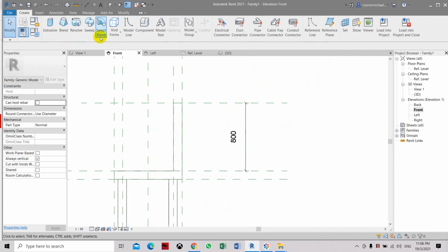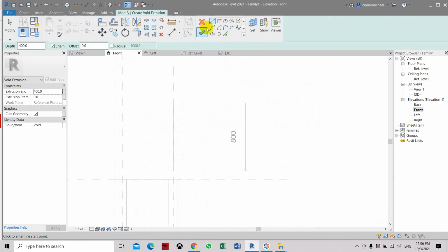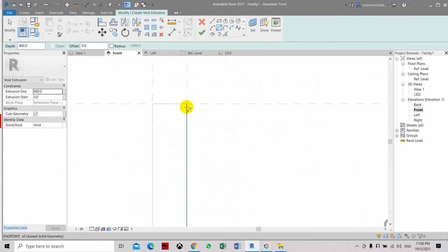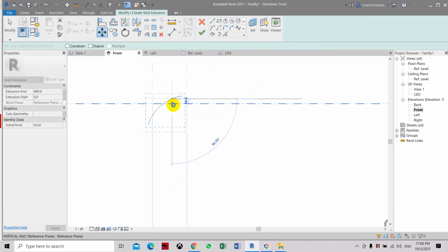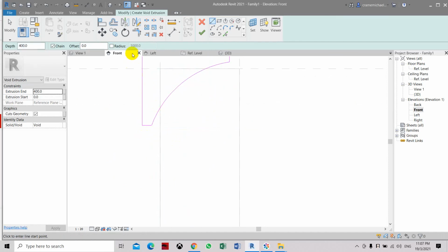Here we can also create a void one or void extrusion. So let's create a shape curving this chair. So let's move this. We're just simply placing it first. Let's create some. It has to be a full loop. Then fillet this if it's not closed.